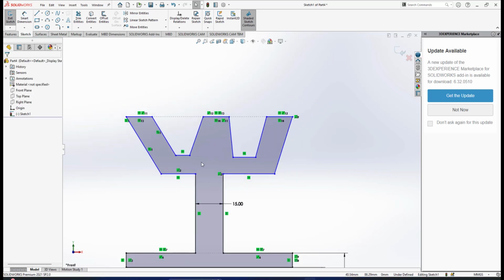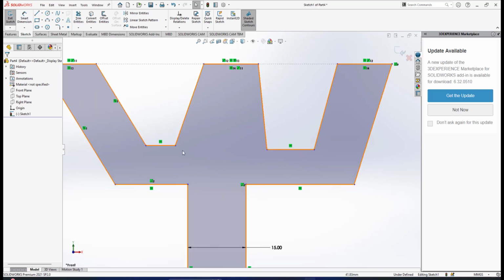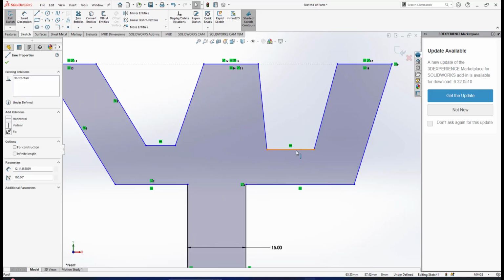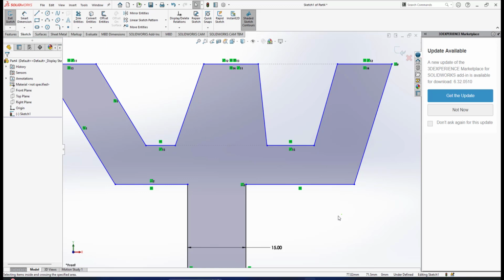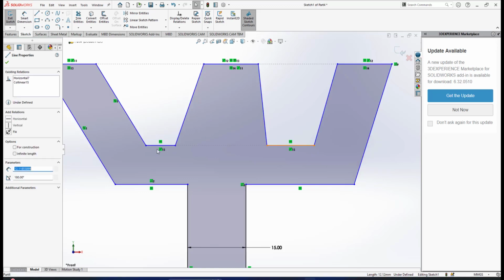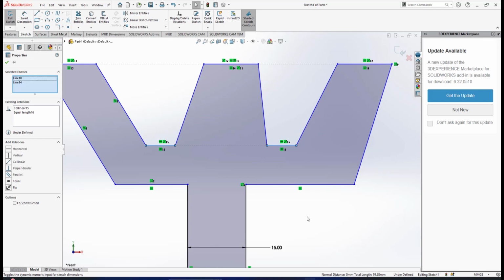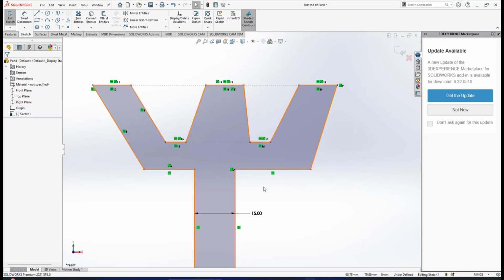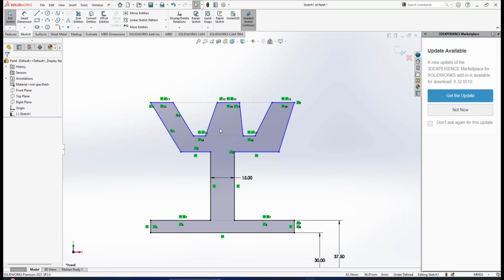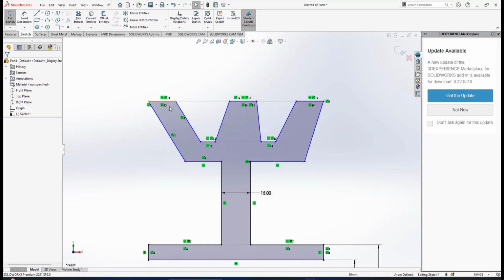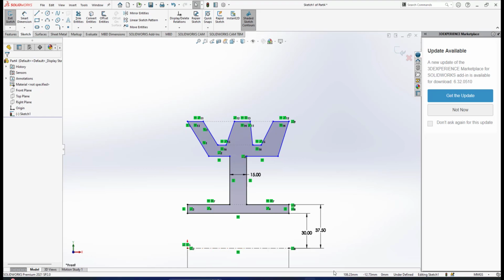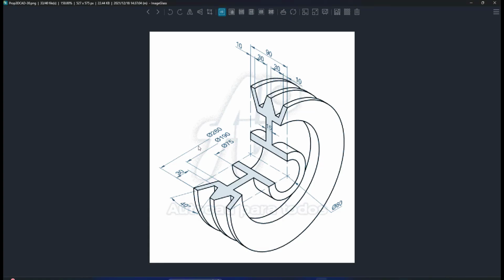All right. The next thing to do is that if you look at this line and this line, they must be in line. So this one I select and I hold control and select this one. This must be collinear. And also another relation, this line and this line must be equal, so it is equidistant. All right, before I do another relation, I need to put what is actually the total height from here to the center line. Okay, if you look here, we have diameter 280, from the most exterior edge to the center line is 280. So it means half of it will be 140.